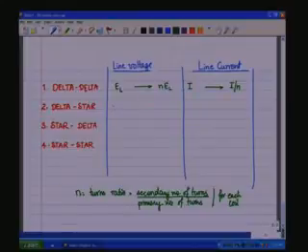In the case of the delta star, we apply a voltage EL. It is the same as the phase voltage in the case of the primary side coil. The secondary side coil becomes N times EL, and this N times EL is the phase voltage of the secondary side star connected circuit, and therefore the line voltage at the terminals of the secondary side transformer is root 3 N EL.